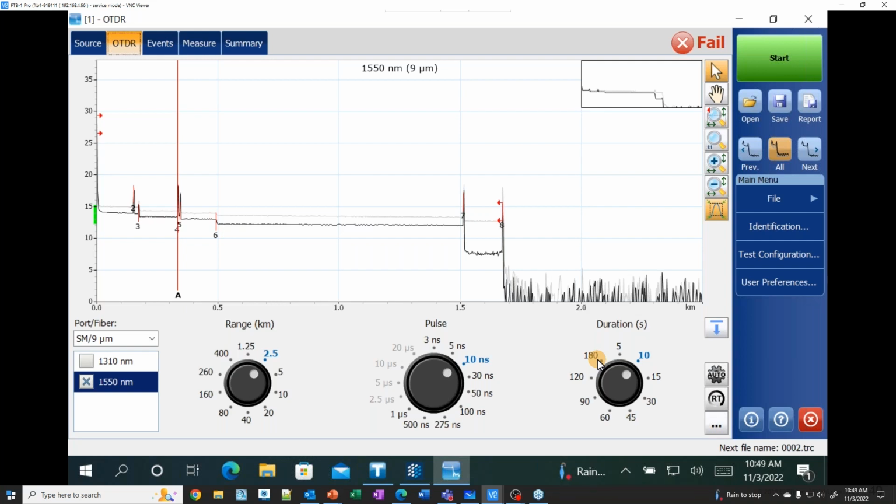in auto mode close to a transceiver like an SFP, say you're at the base of a tower and you shoot up, in auto mode, OTDR manufacturers auto range at a very high power, 20 microseconds. So you're shooting out like plus 15 dBm of light for a fraction of a second. Because of the nature of DWDM optics, you can actually blow that transceiver out.